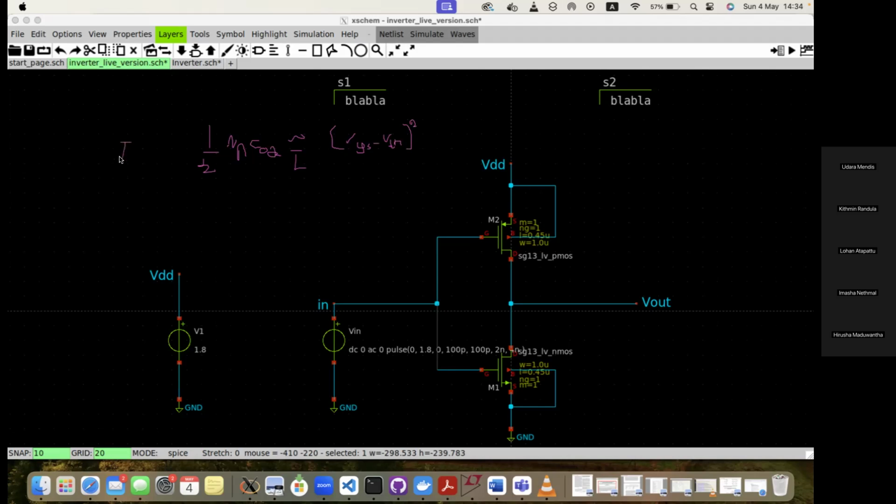These are the most common equations you use, and there is another separate equation for gain calculation, which you can learn during the courses. These are all constants. You need to change the W over L ratio to get the desired current. Most commonly VGS is constant, because you cannot have many VGSs in your IC as you have separate pins and there are constraints, but you can change it. W over L and VGS are the changeable parameters; the other things are constant.